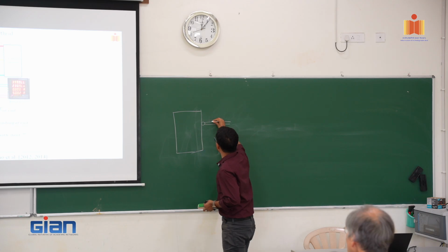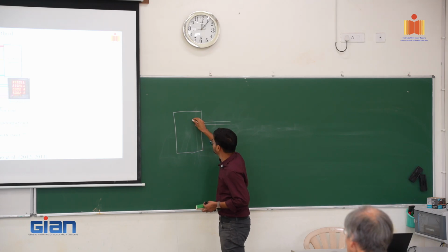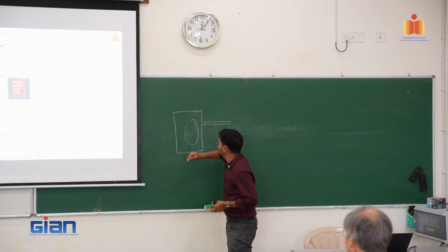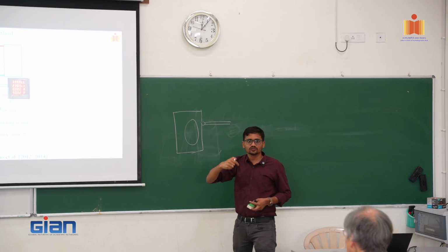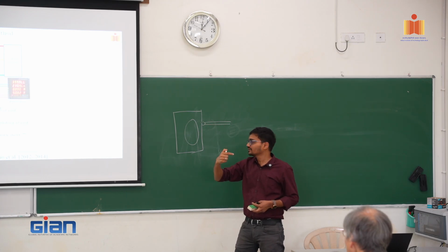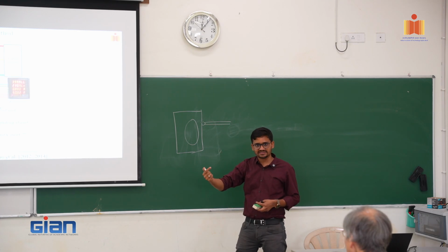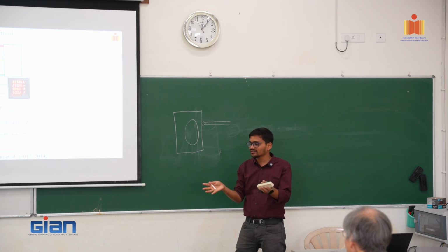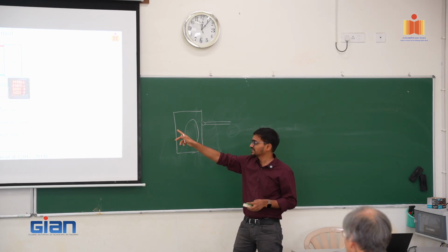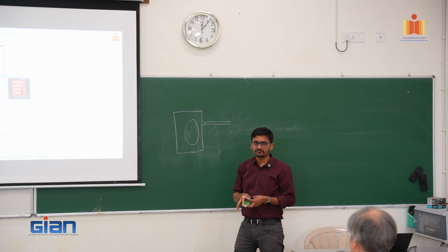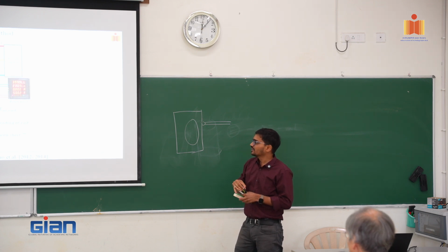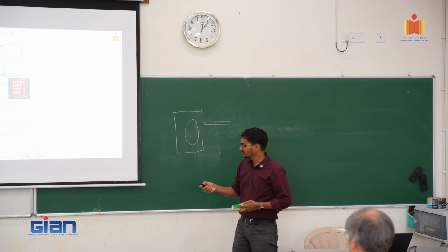Now the tool is engaged with the workpiece, it is moving in a given direction, and simultaneously the tool is moving as well as the plastic energy for the deformation is taking place. So both of them are measured by the power meter at the same time.